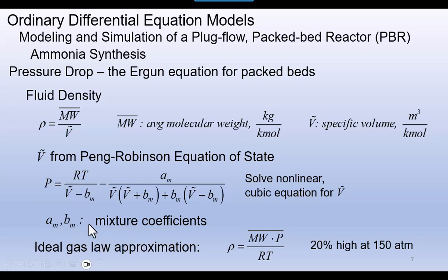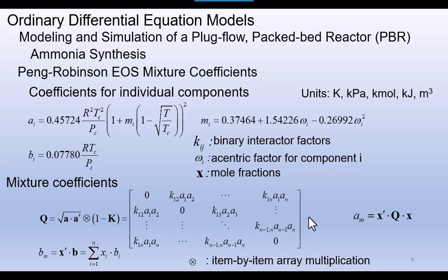We're not talking about a pure component. And we could try to use the ideal gas law as a simplification, but if we're operating at 150 atmospheres, then we're going to be off by about 20% here, so that's not something that we would want to do.